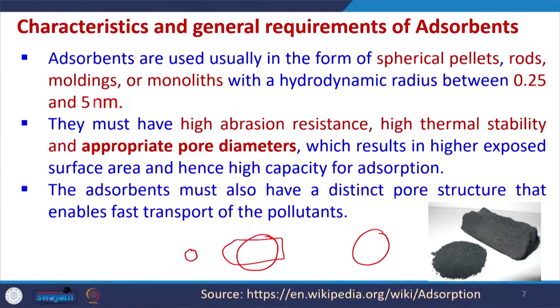So, the same adsorbent may work very well for gas phase adsorption, but it may not work for liquid phase adsorption. Now, in a second case, if the molecular size range is again the same, and we select an adsorbent with an appropriate pore diameter, with a pore size like this, it is possible that the molecules will now go inside and they will reside like this on the sides of the pores. So, this is possible.